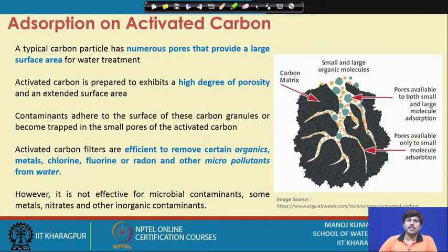Contaminants typically adhere to these carbon granules, or become trapped in the small pores within the activated carbon, and these are efficient at removing various organics, metals, chlorine, fluorine, radon and various other micropollutants. But microbial contaminants, some of the metals, nitrates and inorganic contaminants are not that nicely removed through this adsorption process.